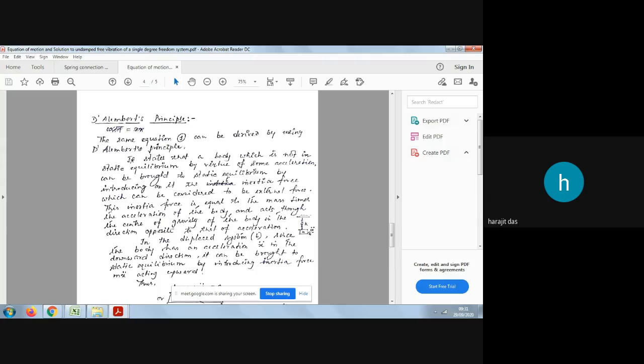Okay, so this is our spring at the displaced condition. This is the mass at the displaced condition. So here the spring forces were k into delta plus x, and mg was there, so mg and k delta will be cancelled out, so kx will be acting upward. And if you apply one inertia force in the opposite direction, which will be acting at the cg of the body. Okay, though here I am drawing the forces, the inertia force will act through the cg. To show it distinctly, we will be writing it by the side.